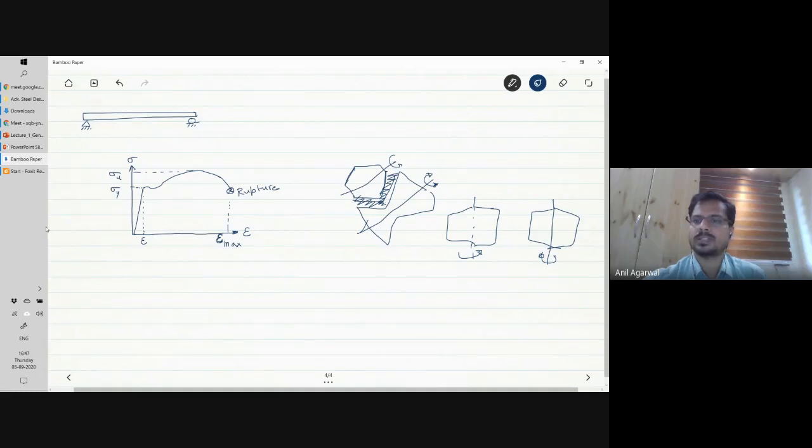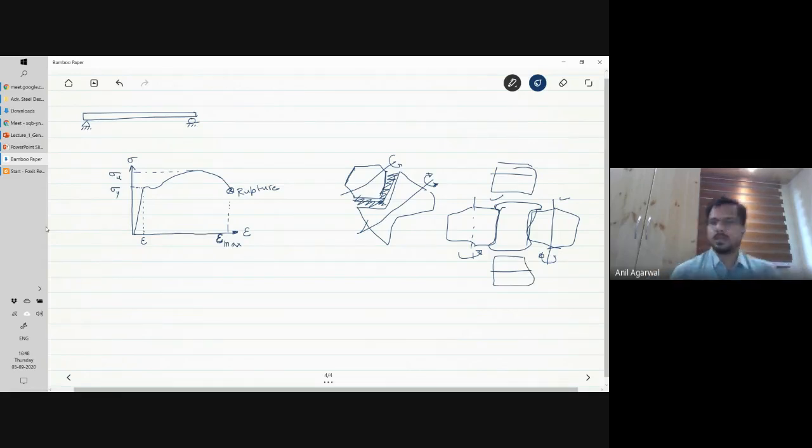So if you have that kind of a section and you gradually bring these two rollers closer, what will happen? Any steel piece that I had put here will start to bulge out, and slowly it will take the shape of an I section, and you can control it by putting another set of rollers on top and bottom. You rotate them constantly and apply the required amount of pressure so that you get the desired shape. That process is called hot rolling.